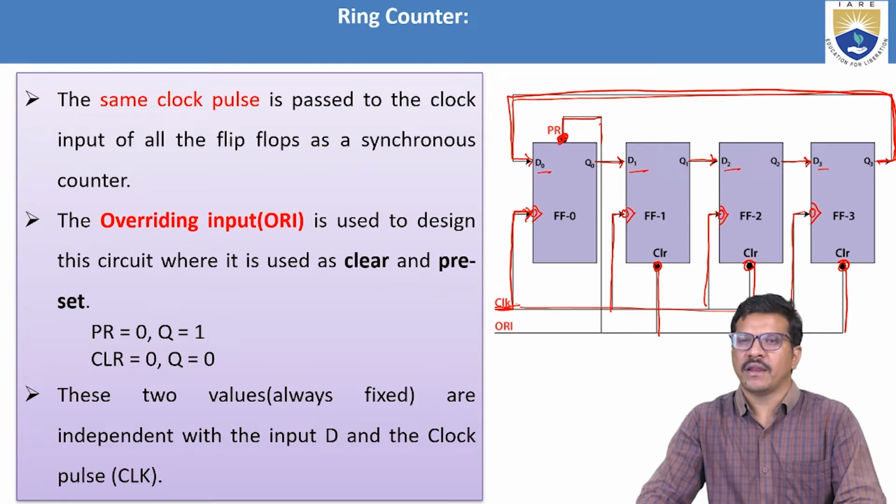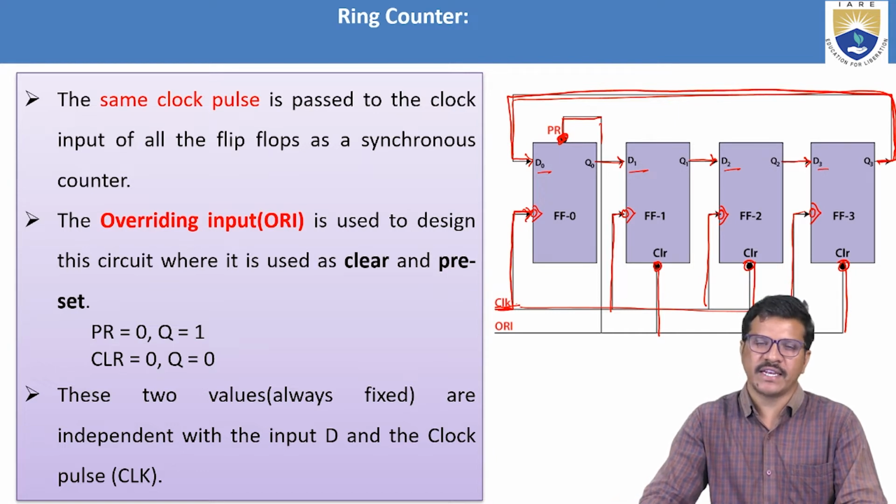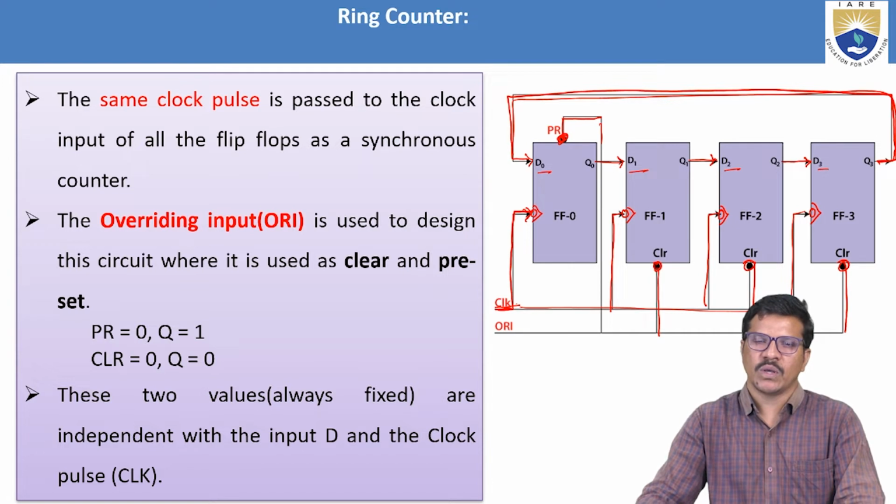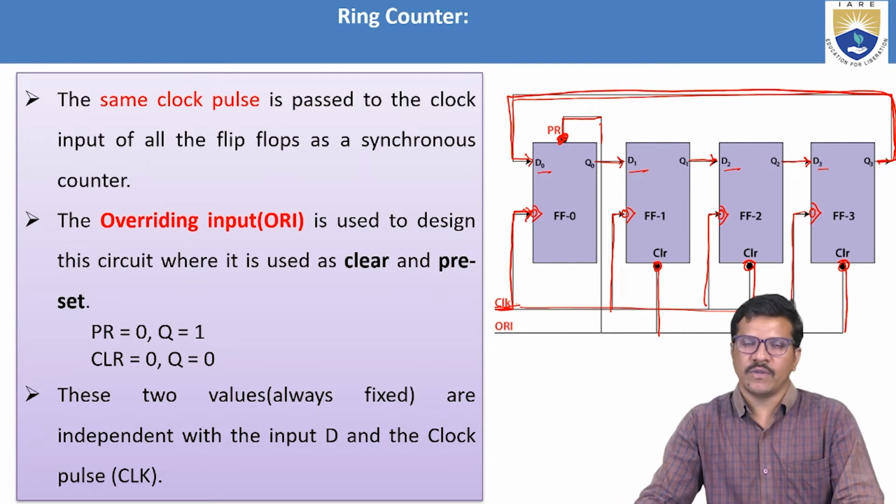They are independent, and it is also just like non-maskable interrupts. So they interrupt the flip-flops at any time. Once they are enabled, then irrespective of the clock and irrespective of the inputs of the flip-flop, they do their job.